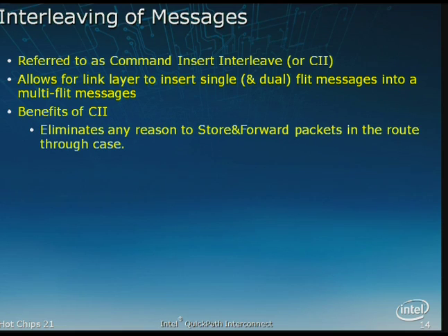And the benefits of command insert interleave. Now that we have CRC on flits, we're allowed to insert messages at flit granularity in between a bigger packet. But more importantly, because we have CRC on individual flits, we don't bring in the entire packet before we route it someplace else, or allow the data to be consumed by the core. We do this at 8-byte chunks.